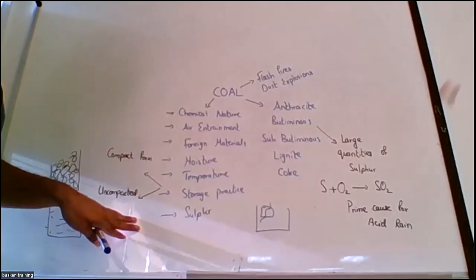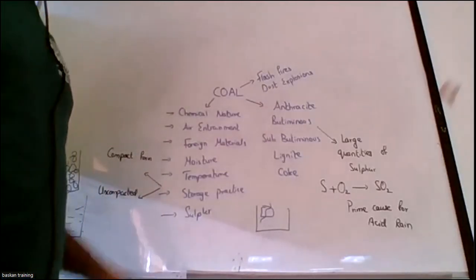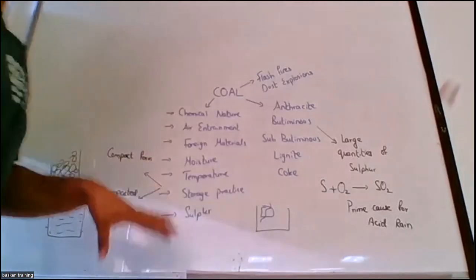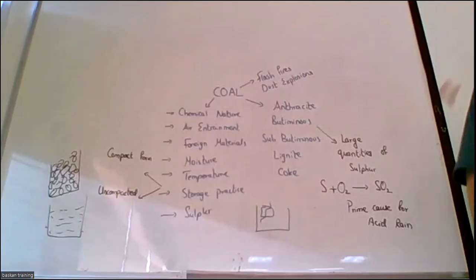So based on that, those are the hazards that are associated with coal. Now, what are the methods by which we can actually control it? If any of these processes has actually started coal fires, it becomes difficult for us to control. Coal fires may take up to 6 to 7 days to control.